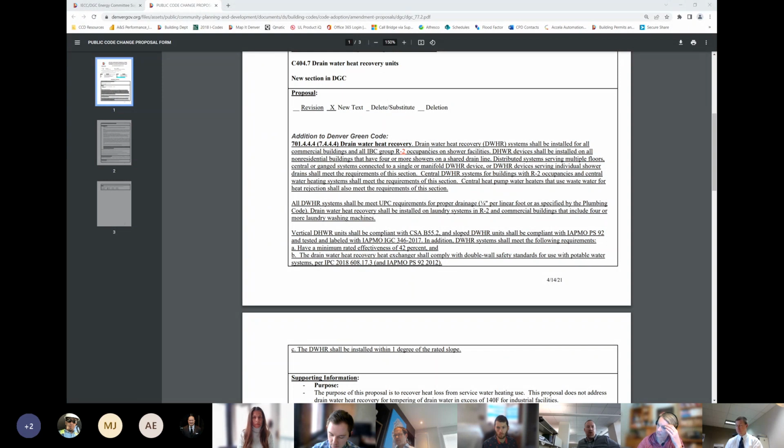And then thoughts on hotels. They are almost exclusively central hot water systems, so I think there's a huge opportunity to use heat recovery in a hotel. Apartment buildings typically are designed with individual water heaters in the unit, so you'd almost have to either intentionally gang it together and have a central hot water system, or have the additional cost per unit to have a heat recovery device in an apartment. So I think hotels are a bigger opportunity.